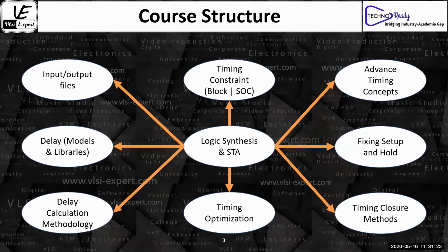More focus is on the input files, because if you have a very good understanding of the input files like .lib, SDC, SPEF, then wire load model, then the technology file in terms of the TLU plus file, and a couple of files specific to the tool and the stages, we will discuss that also. Output can depend upon the flow, so maybe we will not be able to cover all the outputs, but when it comes to synthesis and STA, we will cover those outputs. Don't expect the output files related to verification, but related to front end to back end, whatever the output files are, we will give you an idea about that.